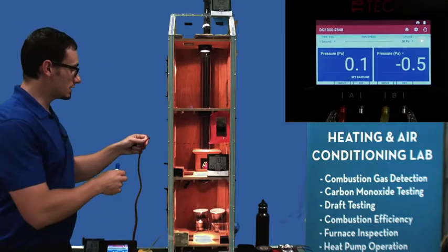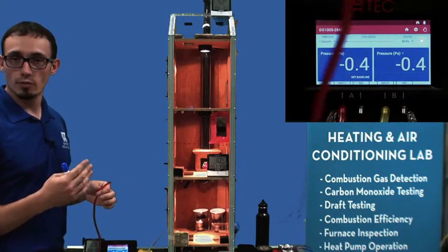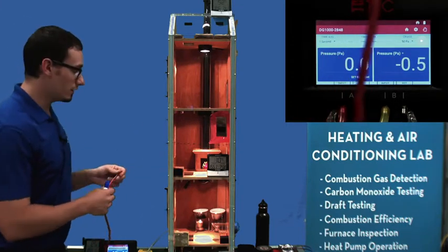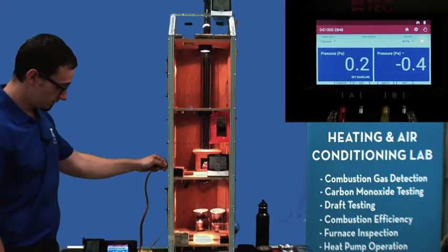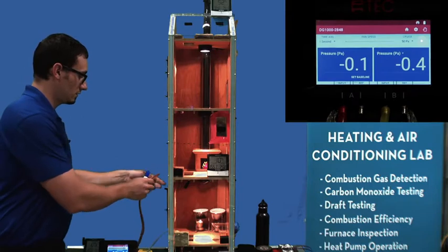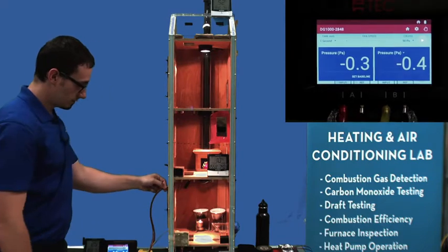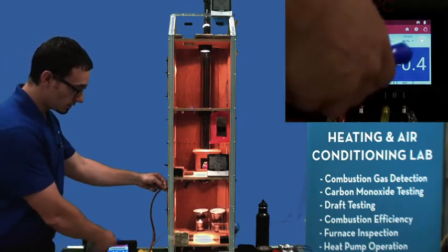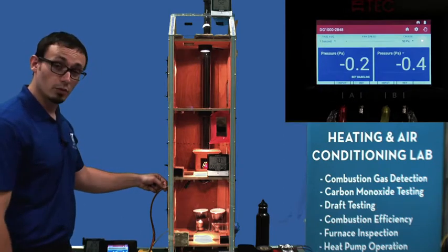And what we're going to see, once I drop below my neutral pressure plane, that's kind of like 0 on my number line. Once I drop below the neutral pressure plane, I should see the numbers become negative. So let's see here. Negative 0.1. Let's drop down again. Negative 0.2. And then you can see on channel B, I've got a probe already at the bottom of the house, and I'm at a negative 0.4.